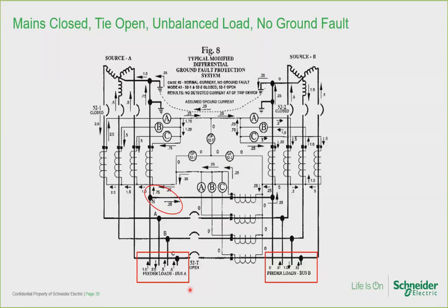Look at the 1 per unit neutral load current flowing into bus A. So this neutral 1 per unit was flowing out of phase A to the loads and now is back to the neutral conductor to the neutral bus. As you see by tracing it upwards, there's a point at which the neutral current reaches an intersection, which I've circled in red, where 0.25 per unit or 25% of the neutral current is diverted to a parallel neutral path to the right, while 0.75 per unit heads up to return to the source A that's supplying this neutral current.